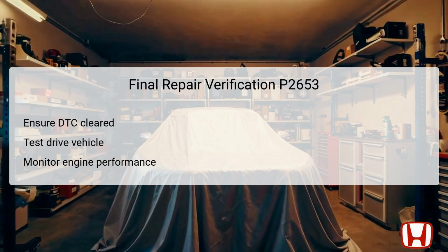During this test drive, monitor the engine performance, paying close attention to any symptoms that previously indicated the DTC. If the DTC does not reappear and the engine operates smoothly, the repairs have been verified to be effective. Regular monitoring and testing following repairs help ensure that the issues do not recur and confirm system integrity.